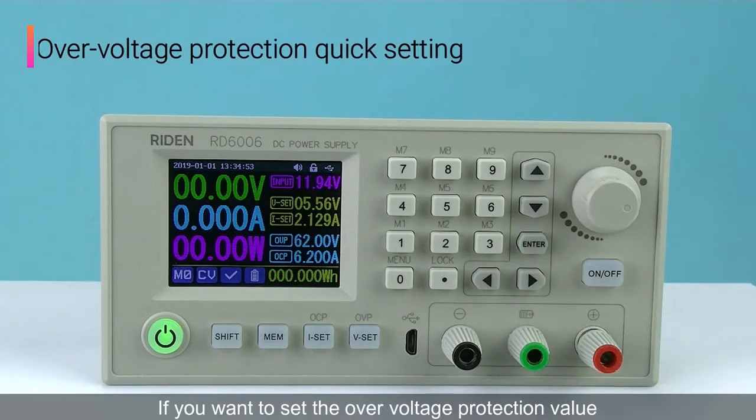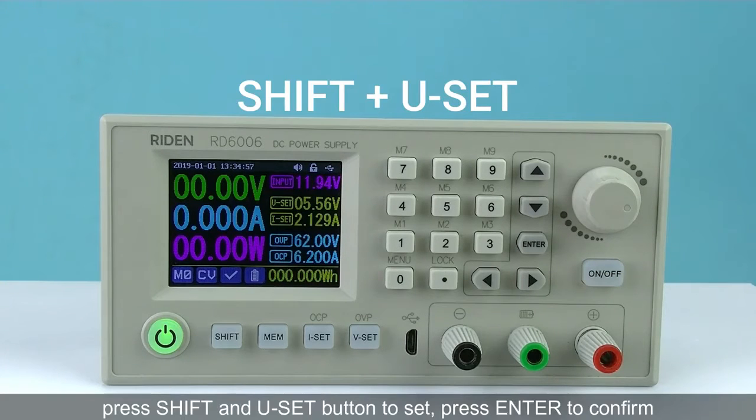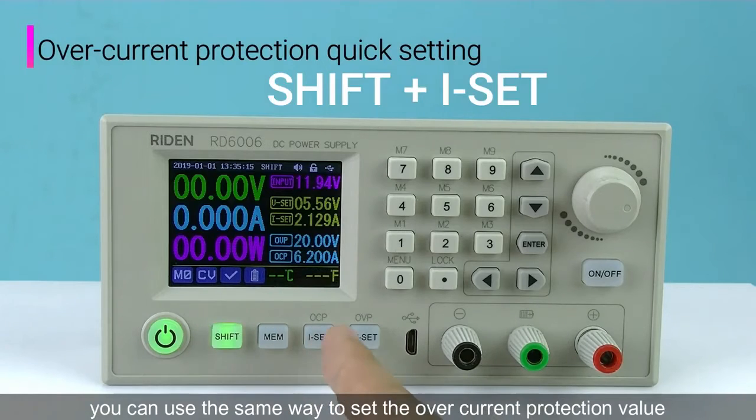If you want to set the over voltage protection value, press the Shift and the V set button to set. Press Enter to confirm. You can use the same way to set the over current protection value.